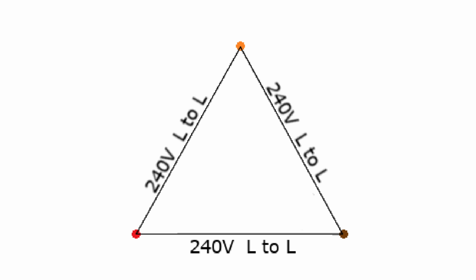Here is another delta three-wire configuration. Now in my experience, three-wire delta configurations are quite rare. The Y configurations are by far the most common form of three-phase power. The last three-phase power we will talk about today is the four-wire delta configuration. This is relatively uncommon, but it is actually much more common in my experience than the three-wire delta. This configuration is most common in older light commercial as well as in large ranch homes, where they require three-phase power for the ranch, but they also want to supply the home off of the same service.